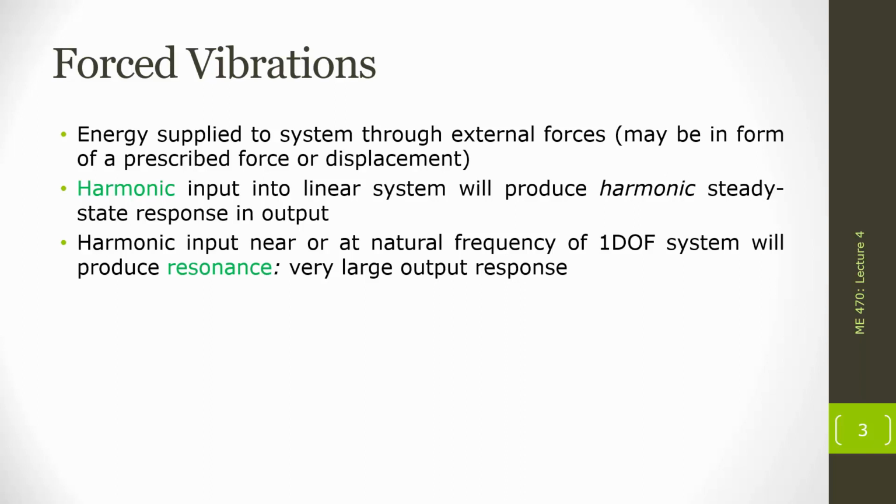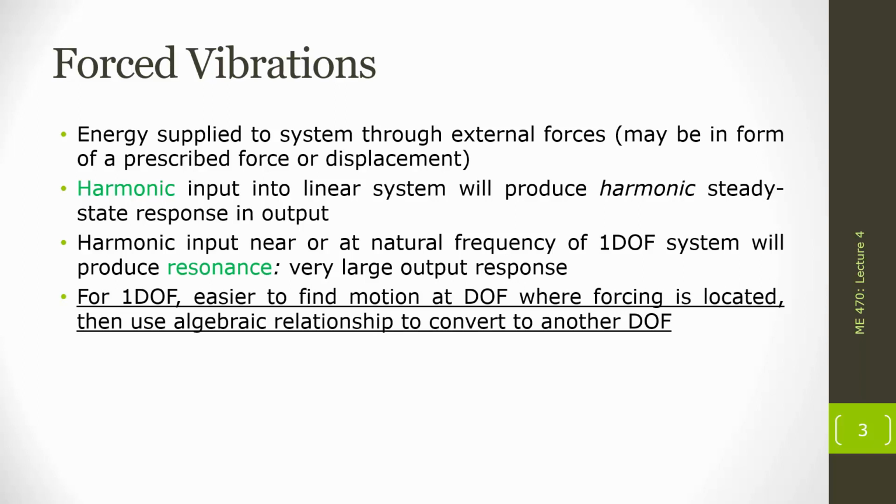And when we're modeling these systems, it's going to be easier mathematically that wherever our forcing is acting, whatever degree of freedom it's acting at, that we want to create our equation of motion and solve our equation of motion at that degree of freedom. So again, we might find it convenient to add additional degrees of freedom to create our kinetic energy, our Rayleigh dissipation, our potential energy, but solving in terms of that degree of freedom where the force acts or where the displacement is located is typically going to be easier. Now, once we've solved for the degree of freedom at that point, then we can relate it back to the other degrees of freedom we might be interested in because we're going to have that geometric relationship or that coordinate transformation already done.